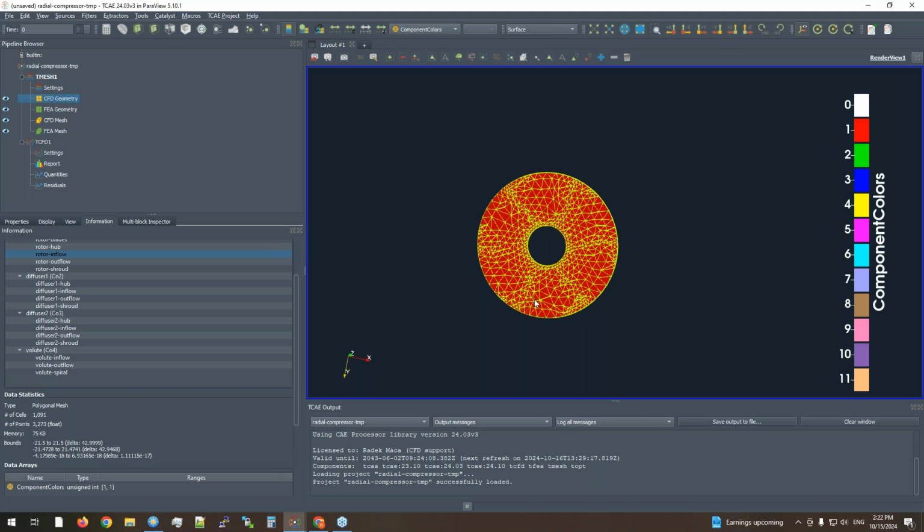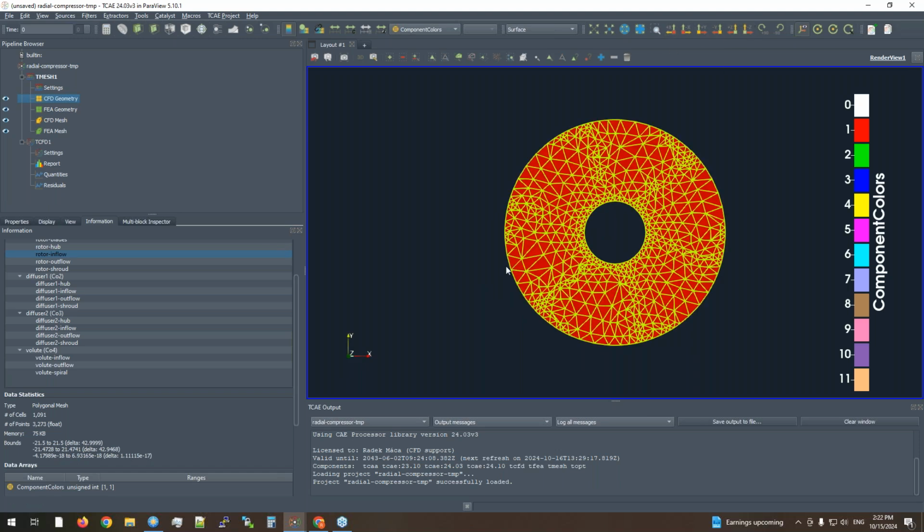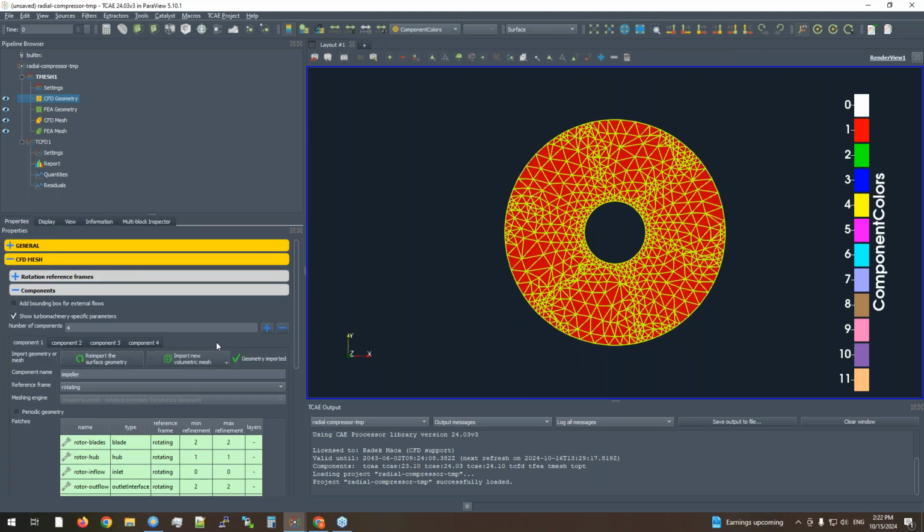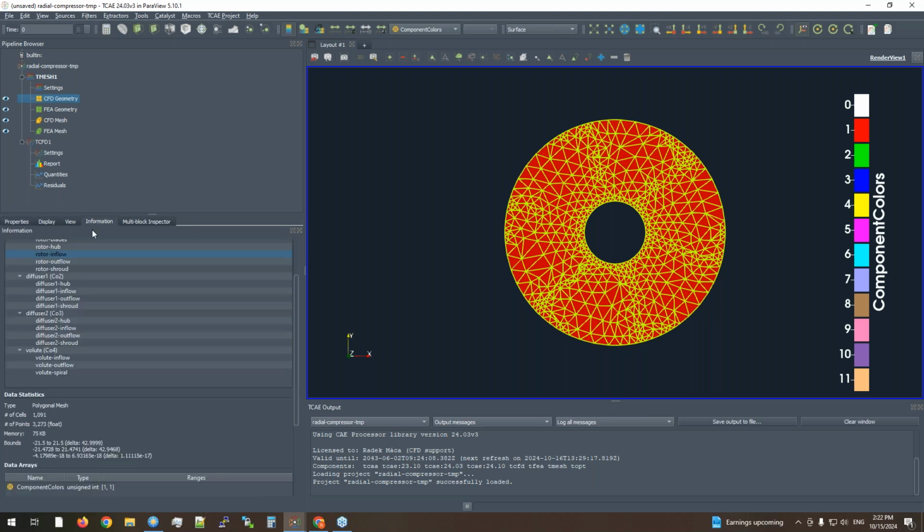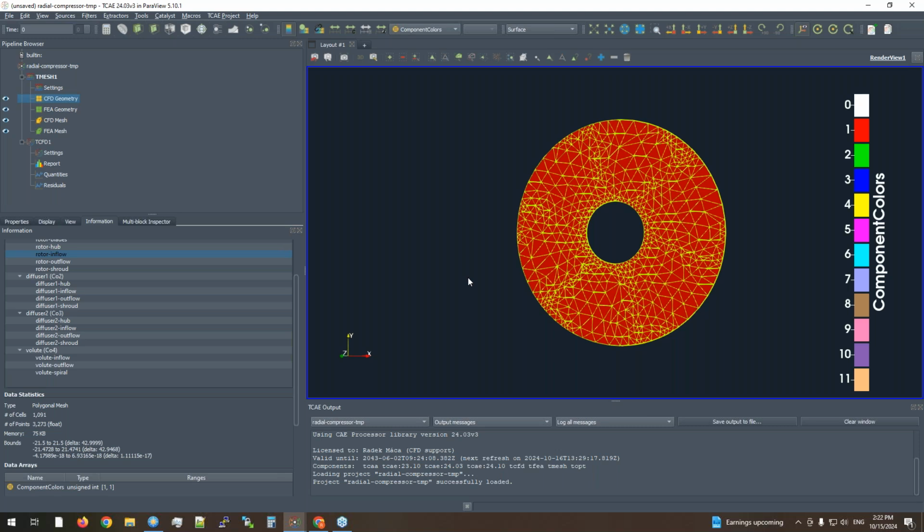And if I would like to check the inner radius, so let me go here. Here we can choose this hover point, and we can check, for example, one of these coordinates. So it's something like the maximum y coordinate. So 6 millimeters is the inner radius. So knowing these values, we can quickly create geometry which will correspond to the inlet extension of this part.